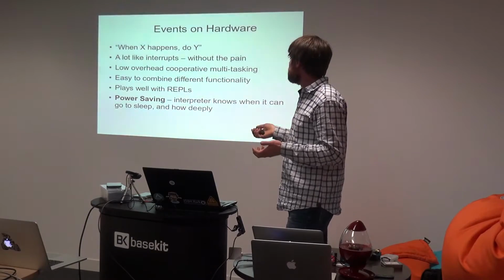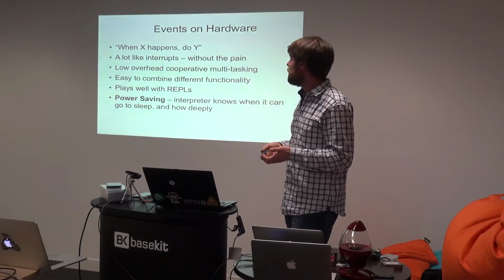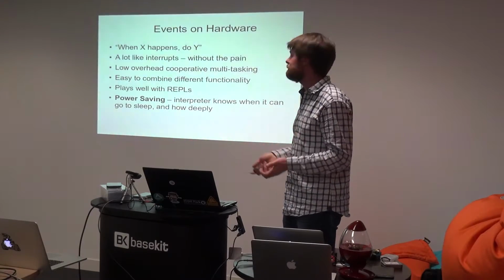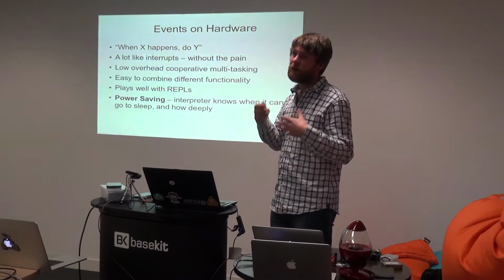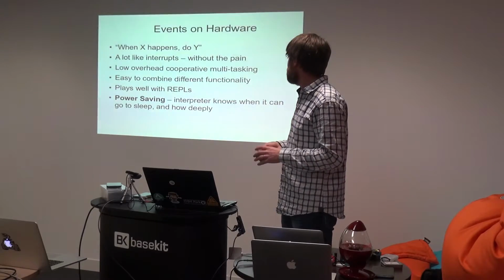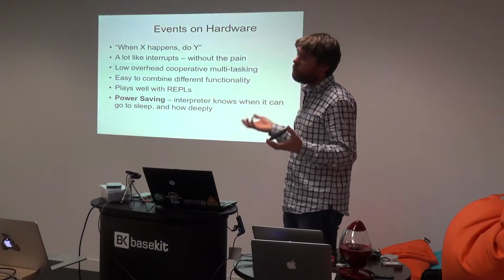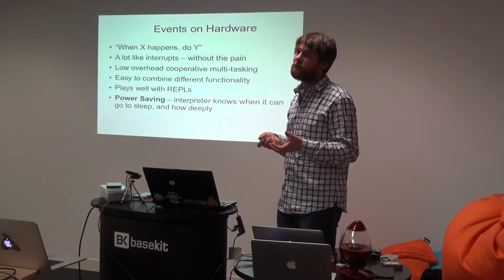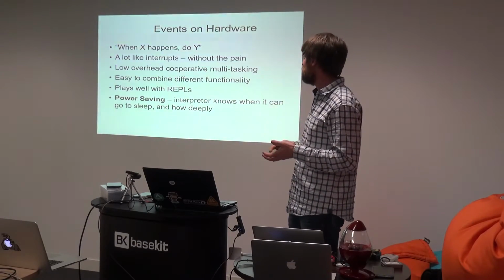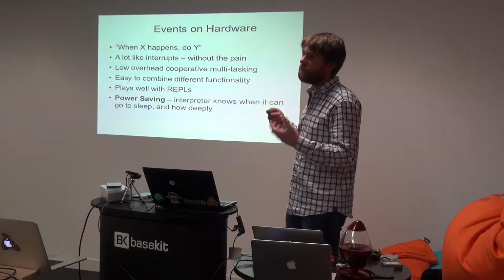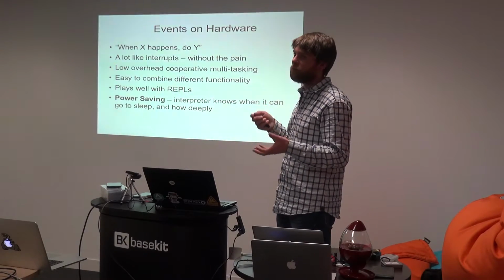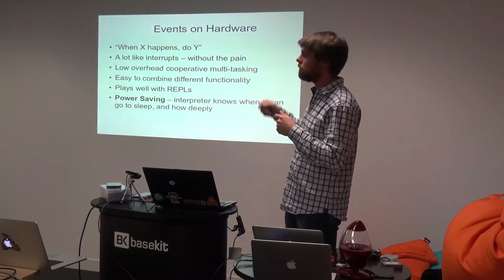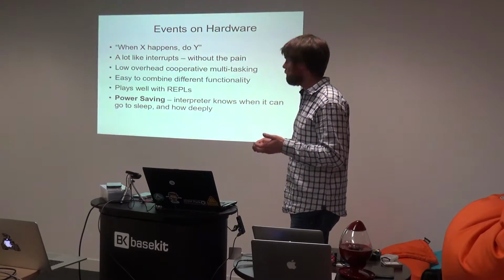The other really nice thing about it is events, which I've covered a bit before. The interpreter can put itself to sleep when it knows it's not doing anything. It's a lot like interrupt-based programming, but if you're using interrupts on microcontrollers, you can get into a lot of trouble quite easily. It's very difficult to test what will happen to your project if your code is preempted at every single point that it could possibly be in, and a lot of bugs creep in.